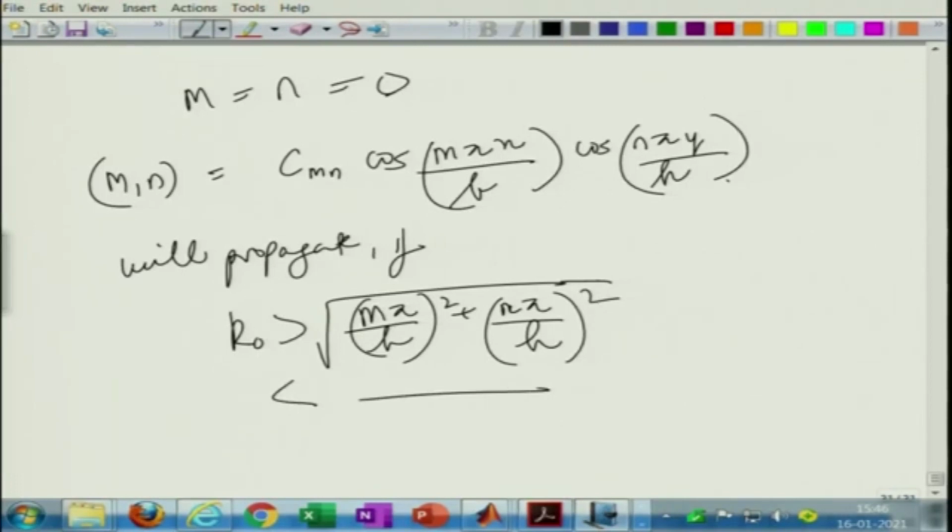You have two solutions, e to the power minus m z, plus some other constant times e to the power plus m z. The part which is decaying exponentially is called the evanescent part, and that will not propagate. What we need to do now is derive the full modal solution. Let us for simplicity assume that mean flow is not there, that is, a stationary medium.